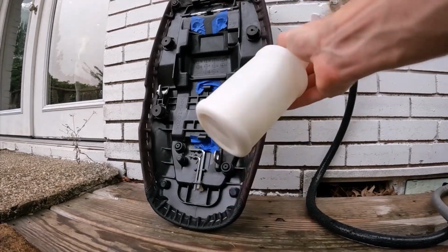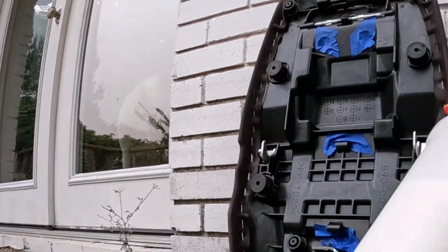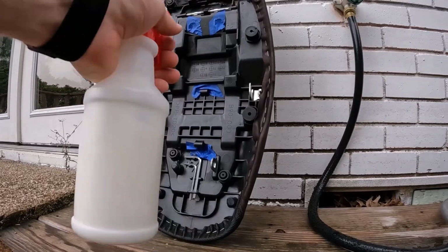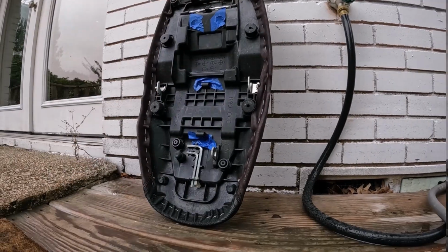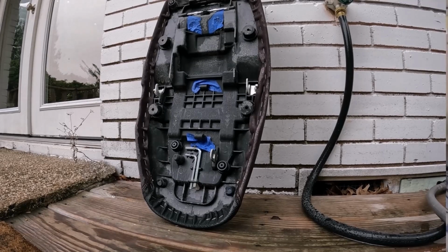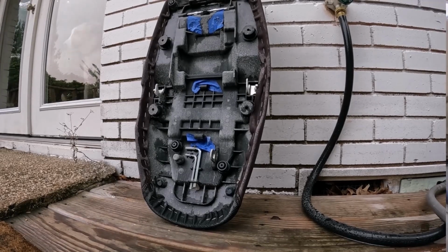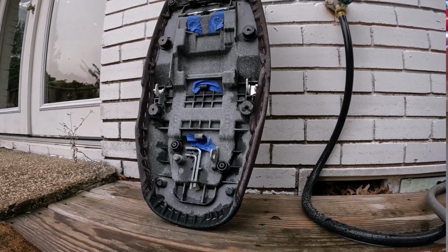Once it's all in the spray bottle, spray down the whole part. After a couple of minutes, the alcohol will evaporate and you're left with a perfect surface for scanning. I do this for everything now. I don't even try to scan first, I just spray it with this stuff. 3D scanners love white powder. Use a lot. Use as much white powder as Robert Downey Jr. used in the 90s. Just don't stick it up your nose.